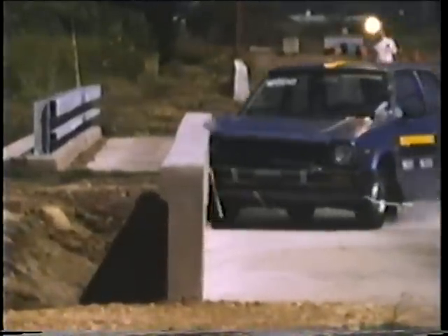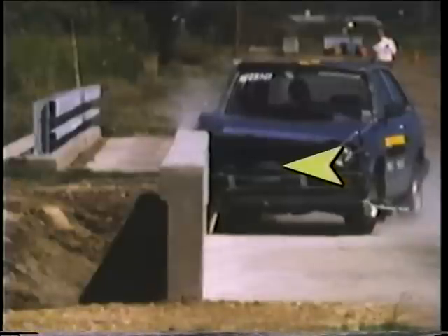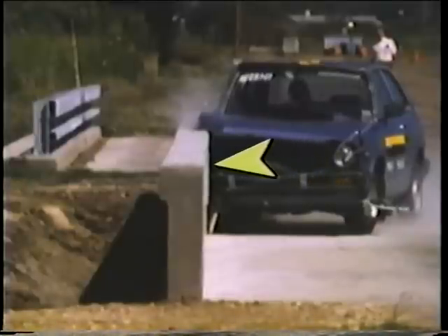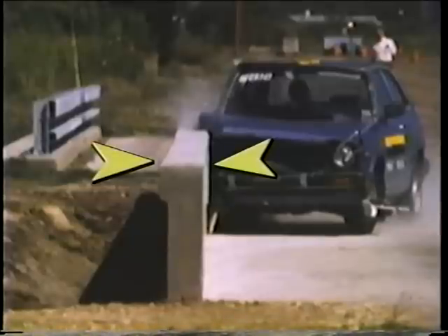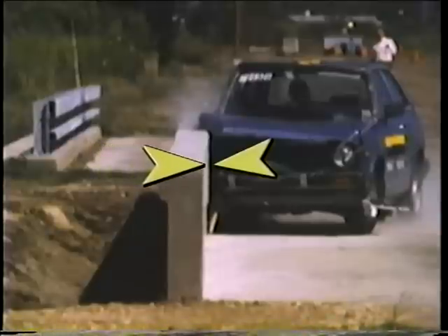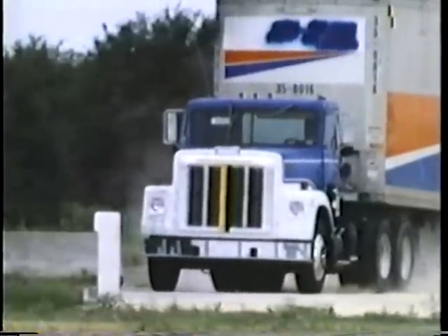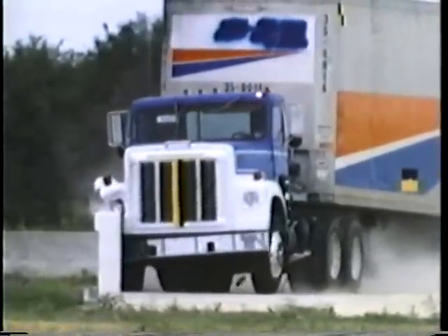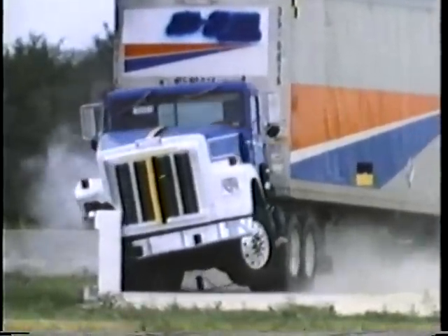In a collision with a typical passenger car, the peak force of the collision may be as much as 60,000 pounds, acting at a height of about 20 inches above the ground. Since most bridge railings are between 27 and 32 inches high, the rail can provide the required force at the correct height for passenger cars. But as the vehicle becomes larger and taller, the height and magnitude of the impact force also becomes higher.